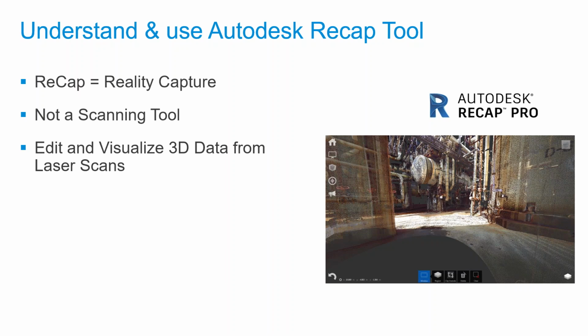You could edit that data in ReCap Pro. When I talk about editing, I'm talking about clearing the speckles and cropping out information which you do not need. It also allows you to stitch that information. When I say stitch, your scanned data which comes from these Topcon or Leica devices is in the form of a number of scanned images, so you have the facility of stitching those scanned images.